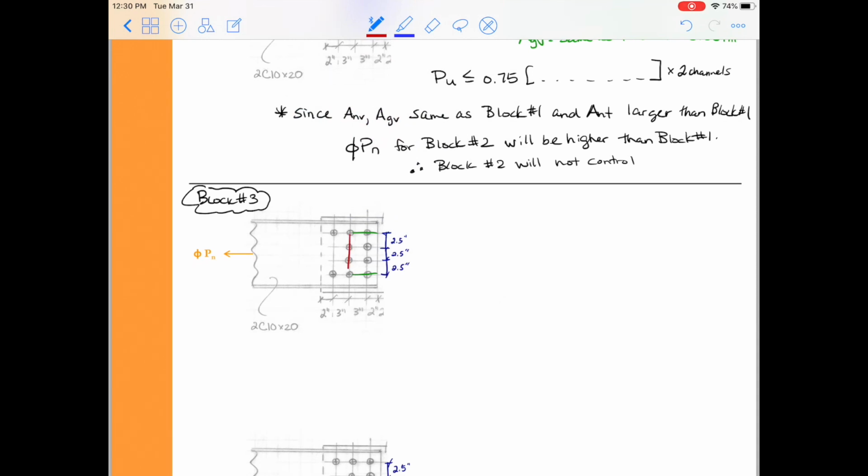that I've sketched. We don't really have to consider the blocks that rip out the sides because, for the channel member, ripping out the side would mean ripping out the entire top or bottom flange of the channel member, and that's not typically likely. So I would focus on these blocks in between the bolt holes, at least for this channel member connection. So go ahead, try these calculations out, check your answers against them, make sure it makes sense to you, and I'll catch up to you in a bit.